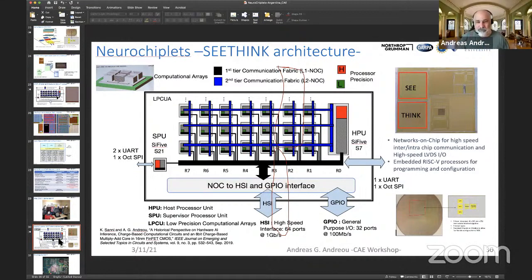So what happened, the chip came back, and we connected the FPGA to the board. They made the board, you see the board. And then they started probing and things started working. We had a few glitches, like the serial port was not syncing, but it was programming the wrong frequency on the PLL to support the serial port. When that was figured out, in 2 weeks we were running computations in this array.